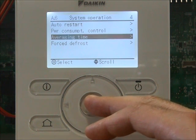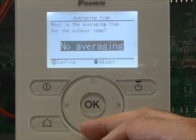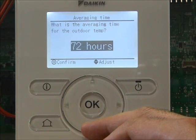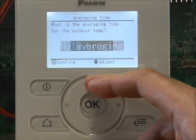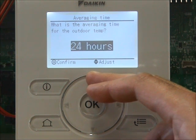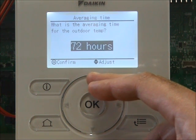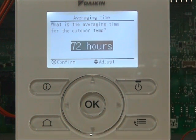We've got averaging time. What's the averaging time for the outdoor temp? No averaging. You can average between no hours, 12, 24, 48 and 72 hours. So let's say we were doing a weather compensation calculation.